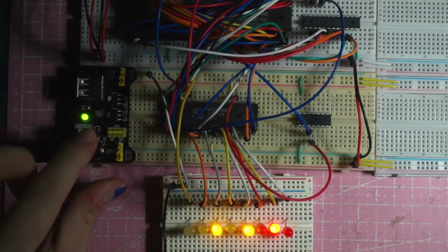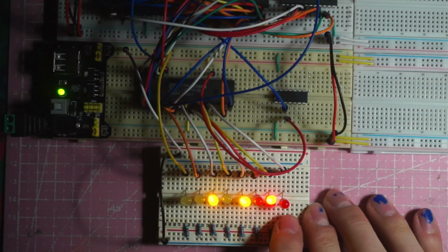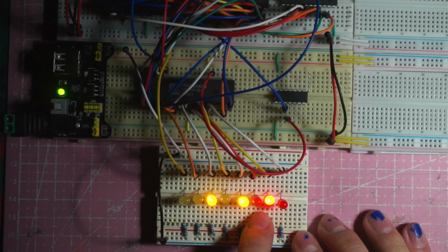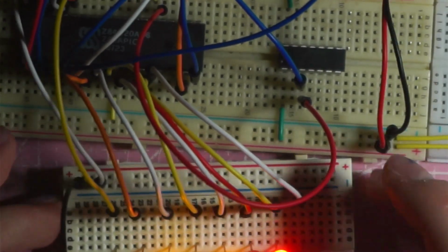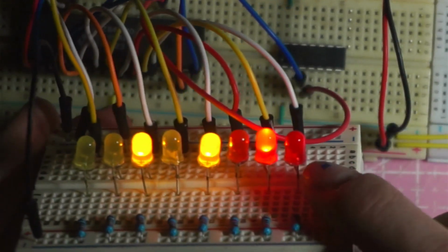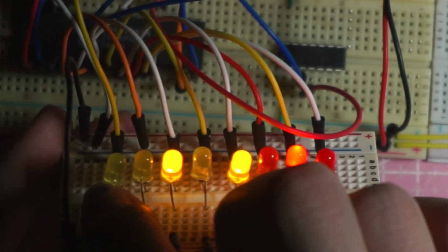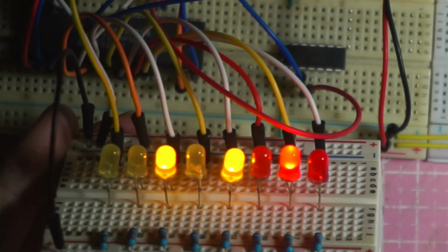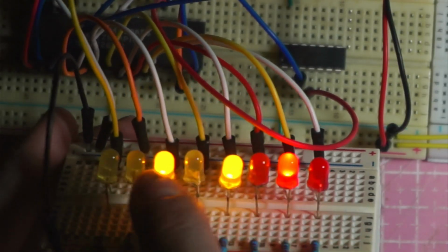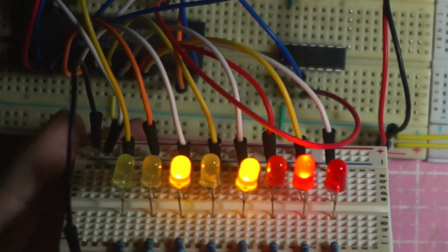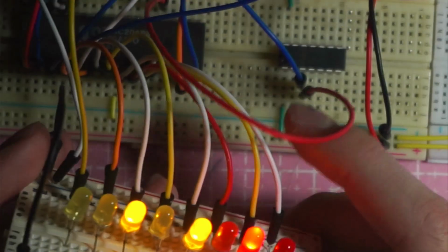and see. Yes, here they are, the LEDs. So A0, A1, A2, A3. I'll zoom in. A0, A1, A2, A3, A4, A5, A6, and this is the halt because I didn't connect the A7. The halt works because it is slow and the halt is active low, and this is the pattern that we have selected in the code. So it looks like everything is working, and I'm really happy.